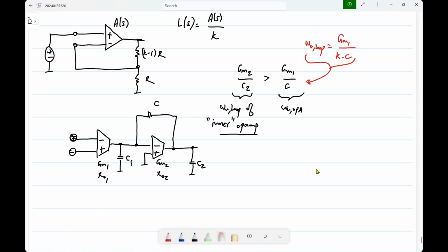And of course, at some point, the DC gain will not go all the way to infinity. It will flatten out at some value. Whereas there are other systems also, as we'll see. In such cases, we know that all the non-dominant poles and zeros must be beyond the unity loop gain frequency, and this statement is essentially saying the same thing. Intuitively, the inner op-amp must be operational over the frequency range where you want the outer op-amp to be operational. Obviously, it should be beyond that.